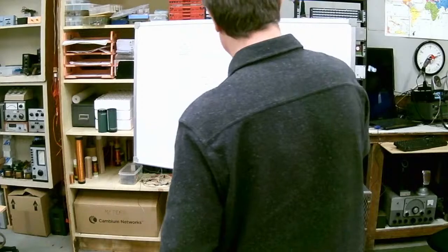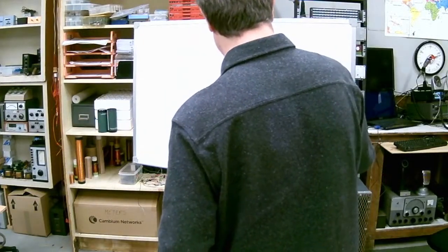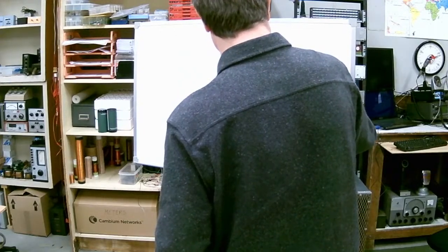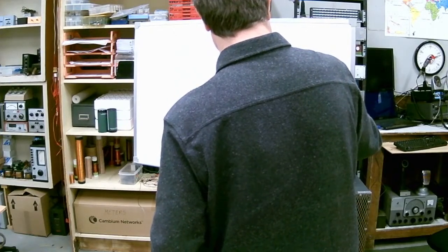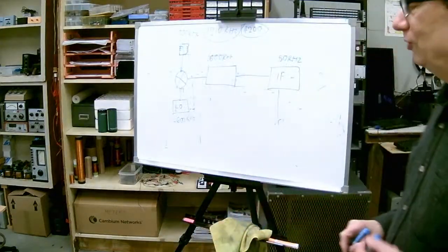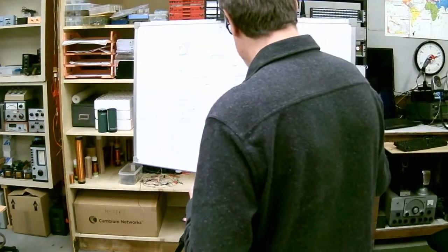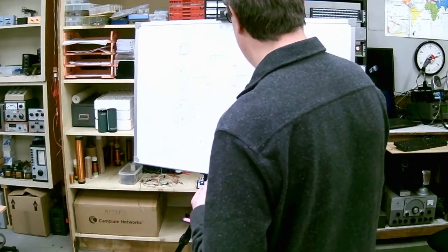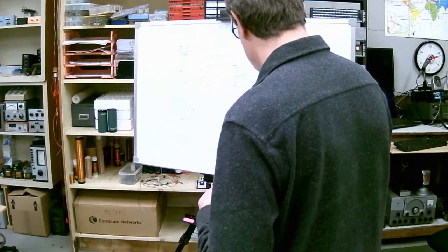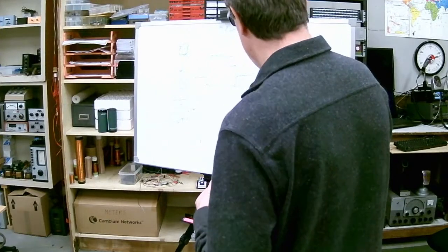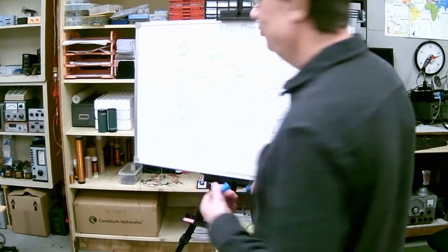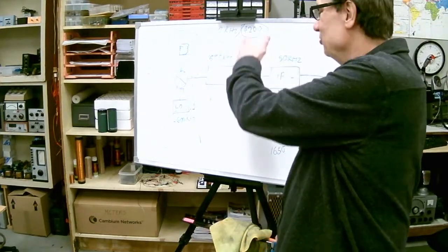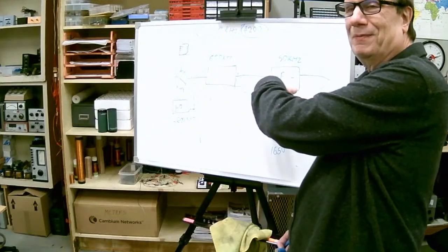So what we did is we had another IF frequency, and this is usually around 50 kilohertz. And you get really high Q circuits at 50 kilohertz. But it meant that you had a local oscillator, which was the difference between here and here. So this would be at like 1650. And the differences between there. Now, the reason you didn't have any images is you weren't allowed any images through here. All your images were already taken care of before they ever got there.